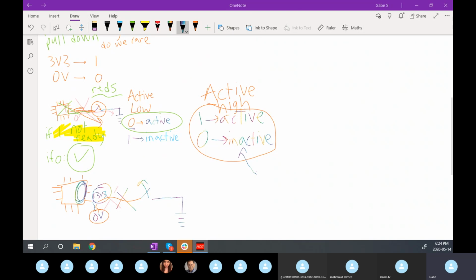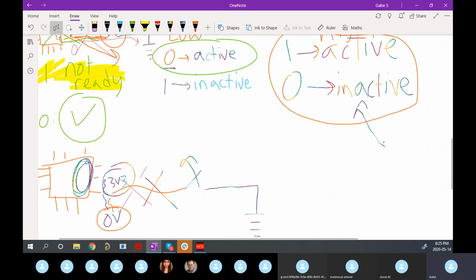And sometimes you don't trust your software configuration, right? Sometimes you never know if it's going to freak out due to the environment, if it's going to be too hot. If, for example, you're going into space and you have a lot of radiation, that can flip bits inside your silicon, and you don't know what impact that'll have on your code. And so a lot of people sometimes just put an external resistor just to be safe as well, right? So you have your internal one configured.